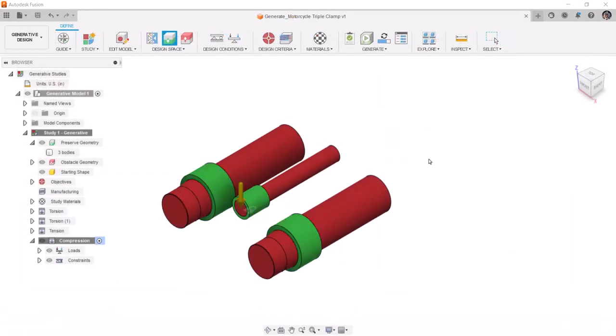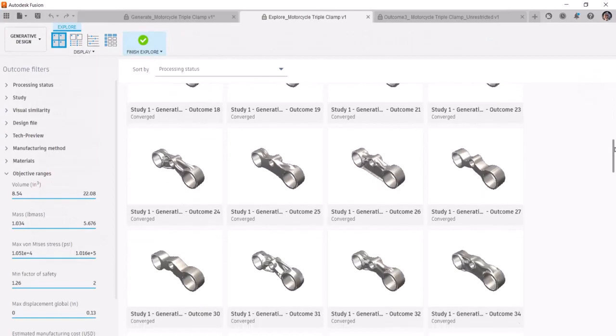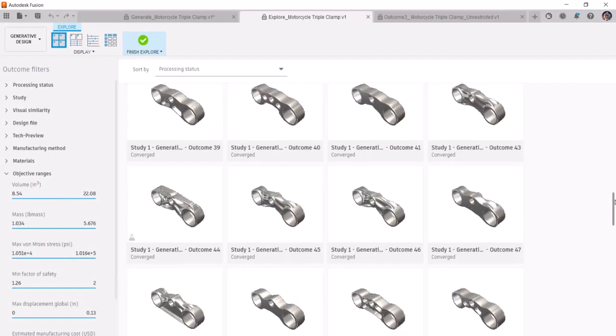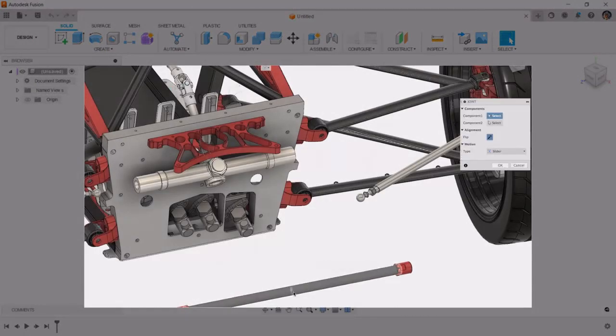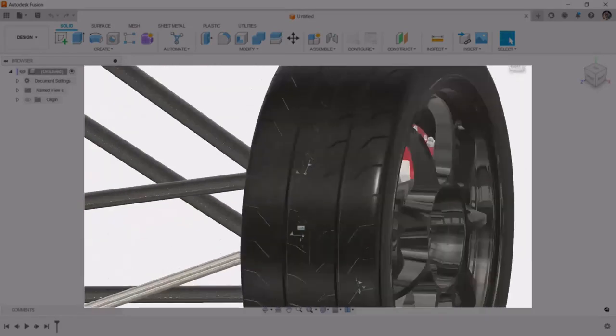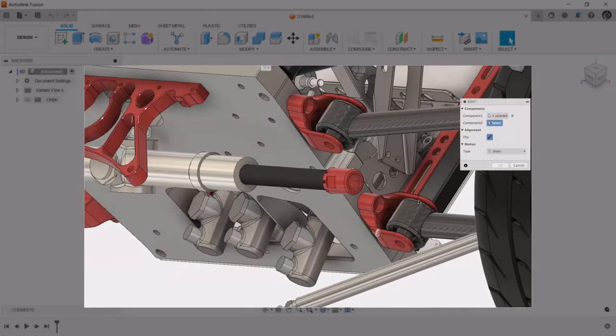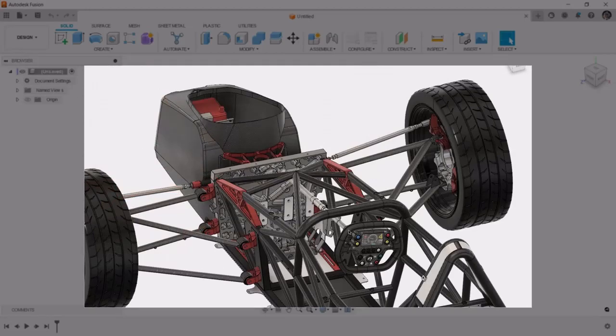Next, using generative design will simultaneously synthesize multiple CAD-ready solutions based on real-world manufacturing constraints and product performance requirements. When you've created your geometry, you can assemble the pieces and ensure the proper motion is captured and constrained. Assembly modeling will let you establish working relationships between the components with joints such as the sliding or rotational joints. With joints, you can limit the range of motion, add cause and effect, and other relationships.